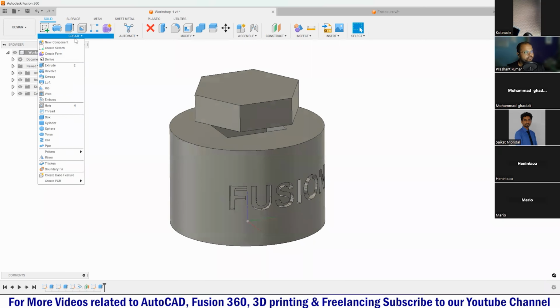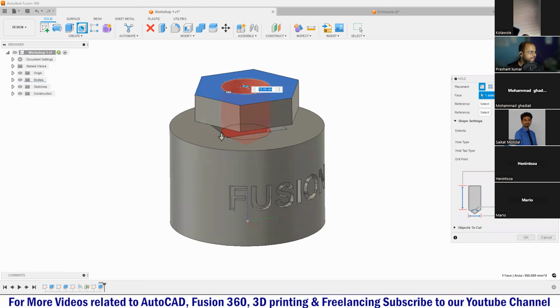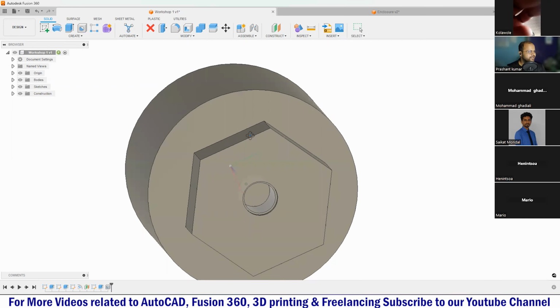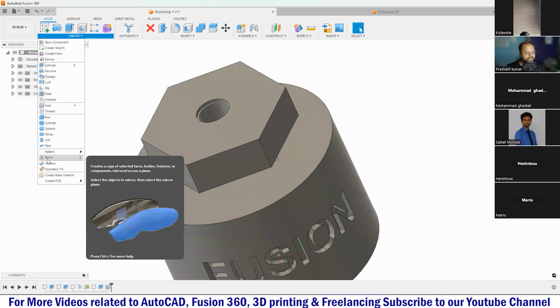For example, we can create a hole. If I activate the hole tool and want to create a hole on this face, I can just select the face and then specify the size of my hole. Also, we can control the hole types, like if we want a counterbore hole, we can select that. We can completely control the size of the hole also. Like if I want the diameter to be 10, I can just change that, and you can see it's getting updated. The moment I press OK, I have created a hole quickly. So for all features, you get different tools.